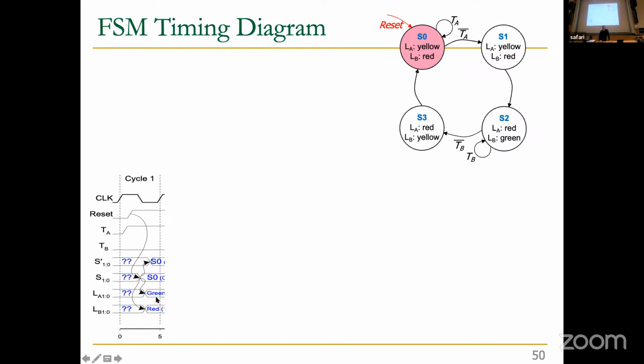Because reset is high, you reset the current state and you go into the initial state. And this happens to be actually a flip-flop with an asynchronous reset, because the reset takes effect almost immediately regardless of the clock edge. So we're going to talk about that when we talk about the Verilog lecture. So reset doesn't depend on the clock, basically. Whenever you reset the machine, it doesn't depend on the clock. So this is not a completely synchronous system from that perspective, but we will talk about that when we talk about flip-flops in hardware description languages.